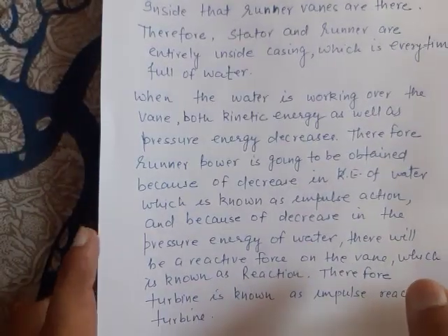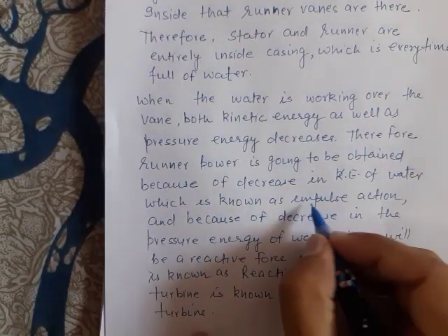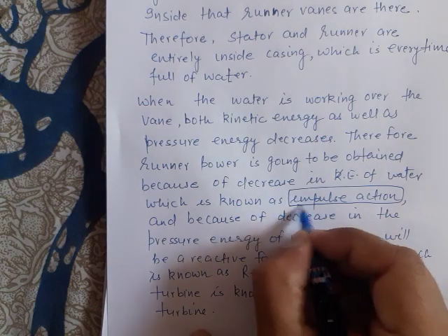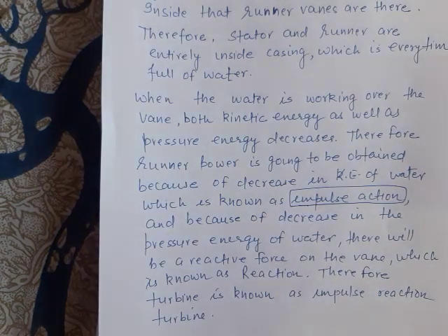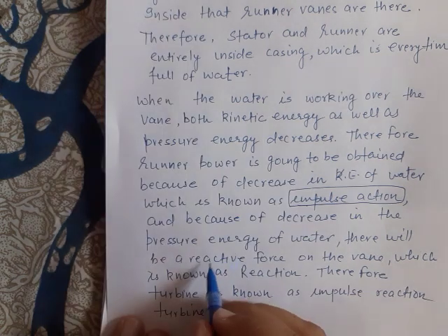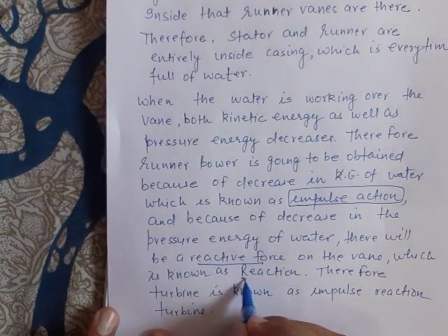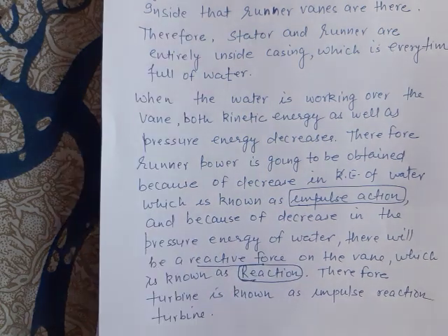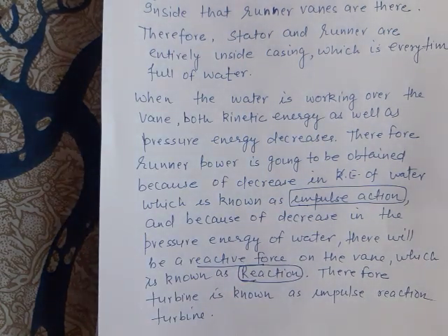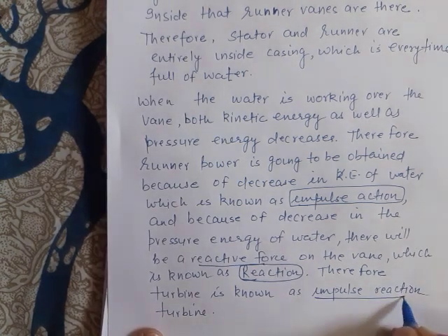Because of decrease in the kinetic energy, we have the impulse action. That's what we saw in impulse turbine. And because of decrease in the pressure energy from inlet to the exit of the vane, there will be a reactive force on the vane, and this effect is known as the reaction effect. And therefore, the turbine is known as impulse reaction turbine.